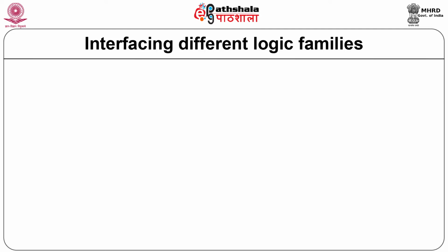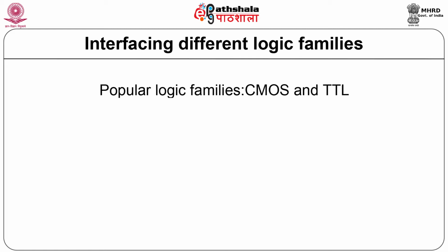Interfacing different logic families. CMOS and TTL are the two most popular and widely used logic families. Although ICs of the same logic family have no special interface requirements, that means one can directly connect the output of one to the input of the other, the same is not true if we have to interconnect digital ICs belonging to different logic families.